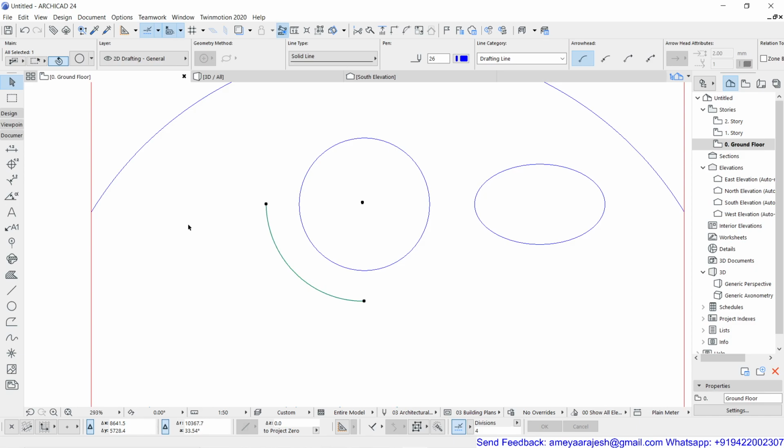Now if I click with the Mercedes cursor, remember that the check mark in the node pet palette was different. If I'm clicking with the Mercedes cursor, this time my pet palette will give me some other options. Apart from the standard 4, I will get radial stretch. What will happen in this case? The overall radius of this particular arc will change as per the new value provided. So if I give a specific value, for example 1000, that becomes my radius. Okay, but altogether the included angle for the arc is the same. It's not changing. The overall chord length will change and the radius changes, obviously.